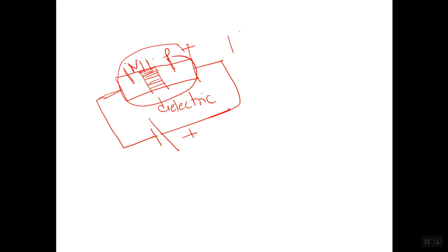As you know, capacitance is inversely proportional to the distance between the plates. It means when distance is more, capacitance is less. When distance is less, capacitance of this particular diode is more. That is the basic concept of capacitance. So here also in forward bias condition, as you apply this forward bias, the distance is less and it means it will be offering more capacitance and its value increases with frequency.